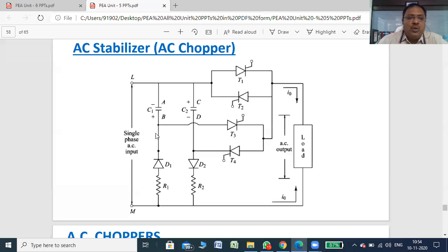So normally, what is the meaning of this? Initially, when the supply voltage starts, as soon as you apply the trigger impulse, this SCR will trigger, output current will flow to the load, and you will get an output voltage. But depending upon the value of this R, we can change the firing angle, or you can say the commutation angle, of the particular SCR.